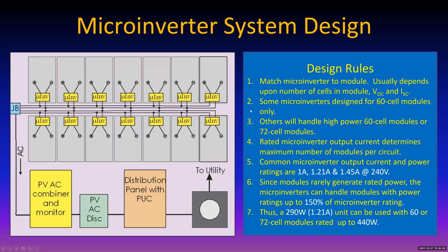So this is your circuit diagram. Here's the rules. That's it. Just that simple. You've got a PV combiner for the microinverters, and the manufacturer generally makes a box that does that for you as long as you have 4 circuits or fewer. Otherwise, you put their data acquisition unit. You use the larger combiner box from a different manufacturer, and you can still use the monitoring unit along with the larger box, so that you still monitor performance of every single microinverter in the array.